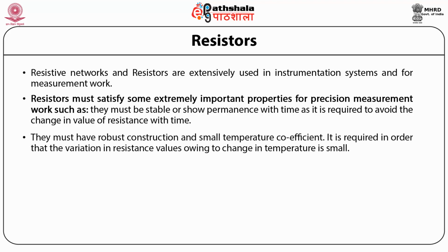They must have robust construction and small temperature coefficient. It is required in order that the variation in resistance values owing to change in temperature is small.